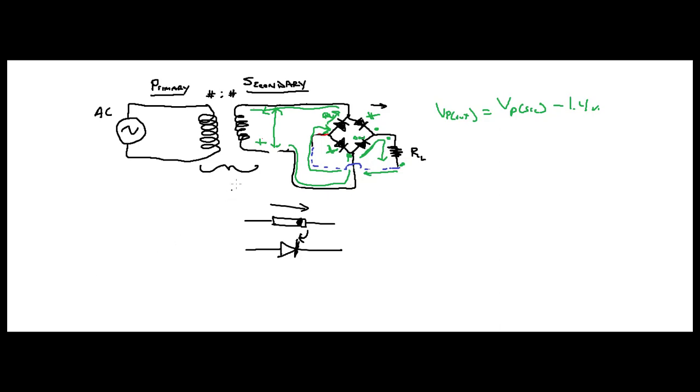Be careful when you're building the bridge rectifier, and make sure that your diodes are all pointing in one direction. All I can say is I've seen a lot of diodes smoked because that didn't happen. I saw one where they had a pair of diodes that were pointed this way and the bottom set was pointed the other way, and it didn't turn out very well. Let's just say there was some smoke in the lab.